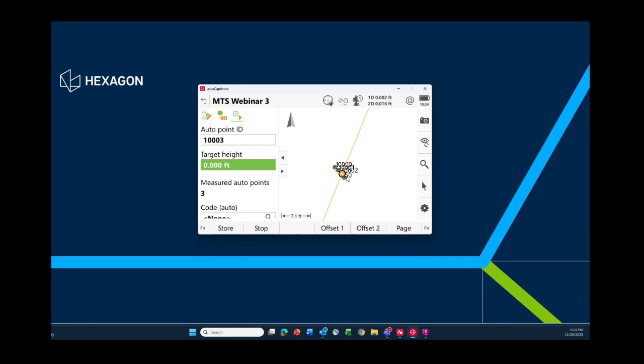But as I move around, it's just like as you walk. This could be useful on an ATV, mount the prism, and then you just drive in a big open field. But I'm not touching any button now. I'm just moving, and I can hit stop right now. That's kind of enough. But again, I measured points here with a foot between them using the automatically measure point.